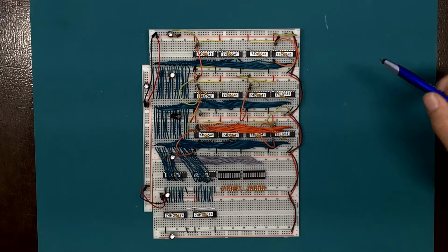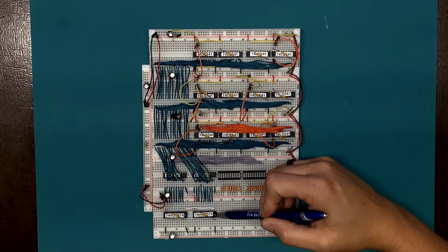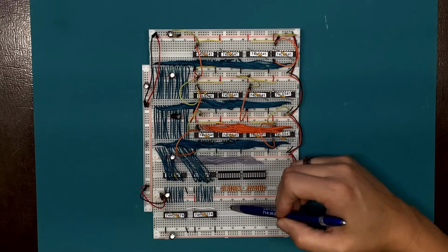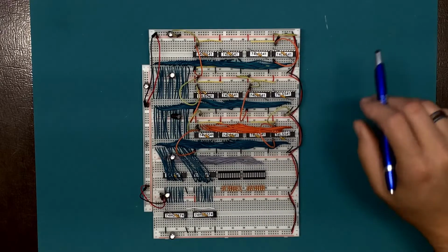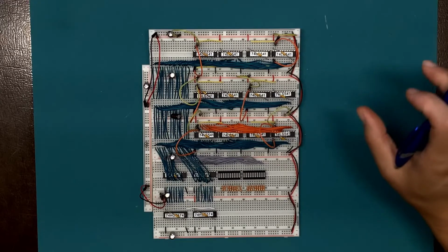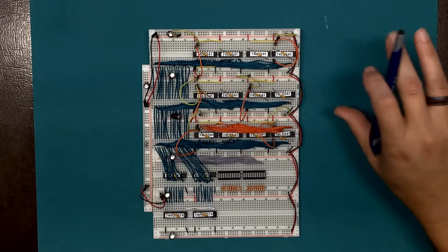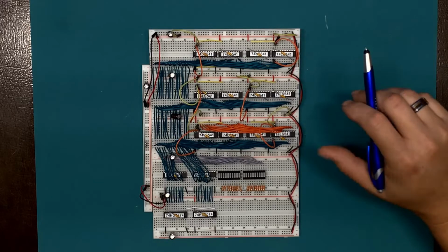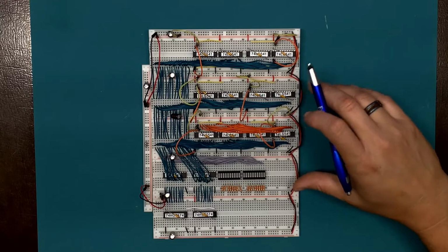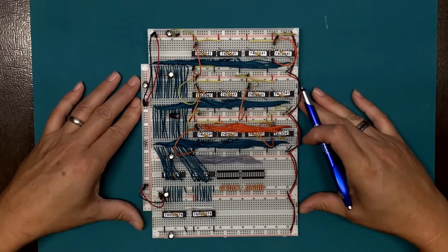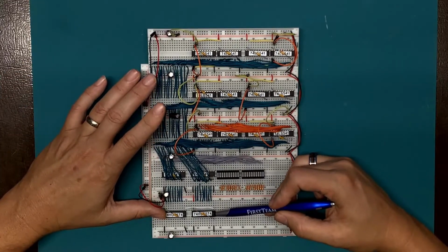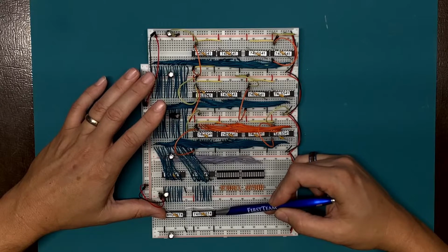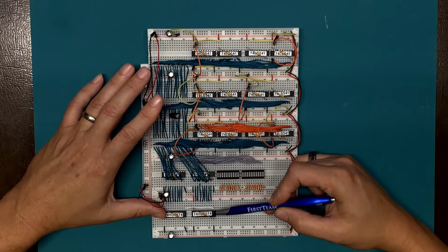Effectively, what that allows me to do is have my address register increment and decrement by 1, and I'm moving it by the entire bus width, 16 bits. 16-bit computer, 16-bit registers, 16-bit bus width. So ultimately what I'd like to do is figure out how to increment and decrement the values on this 16-bit register by 1.